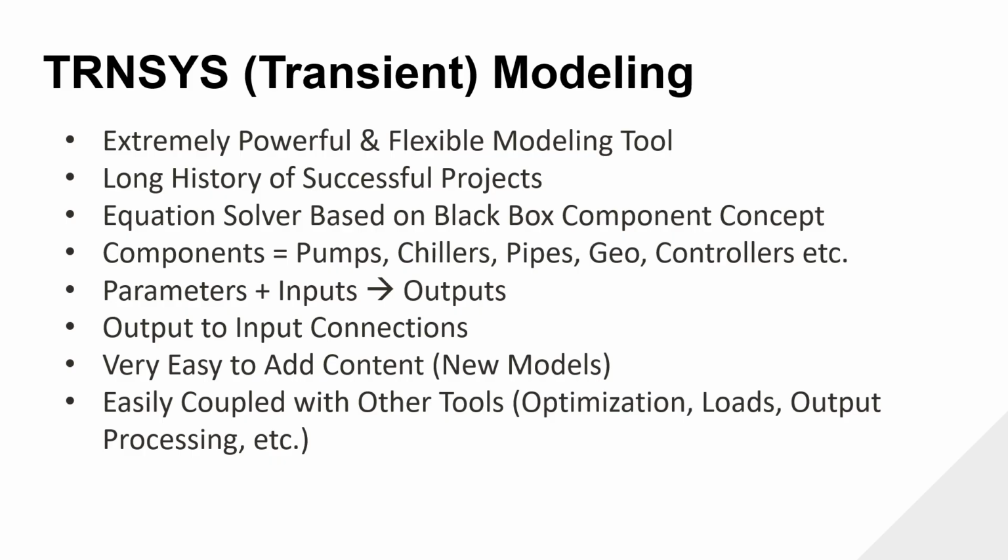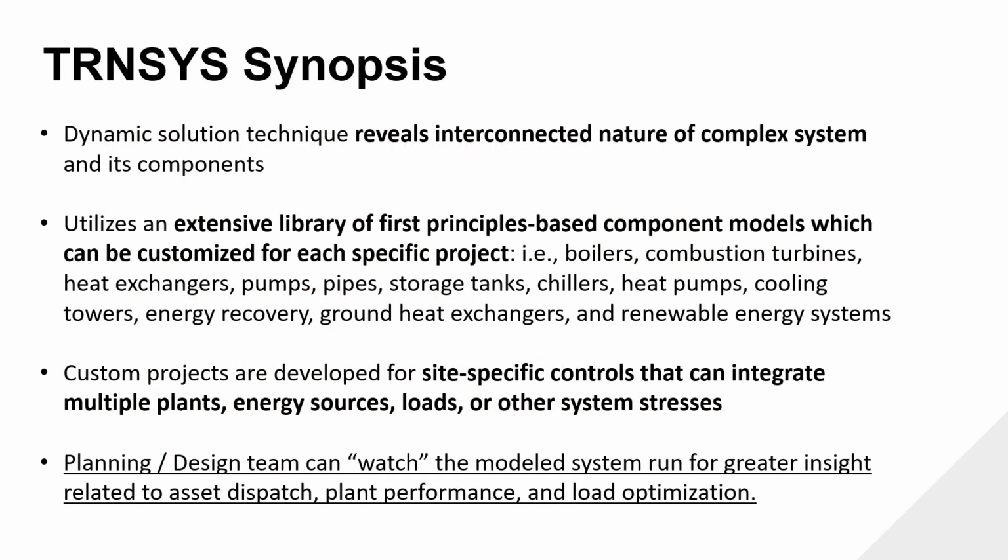The geothermal model in TRNSYS is highly dynamic. It's very flexible. It isn't a static, rectangular bore field. You can design and build it as it's actually going to be designed and built in the real world. So the geometric shape, whether it's inclined or vertical, all your different soil properties, all the things that go into geothermal design, are really critical. You can plug all those numbers in, which is really important for what we use it for, which is almost all of our geothermal projects, whether it's campus and central plant type work or utility thermal energy network type work.